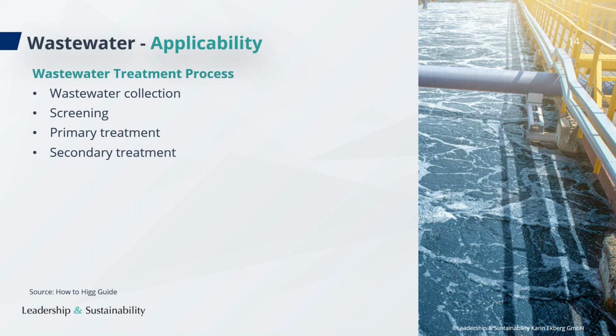bottom of the tank. And in addition to the application of activated sludge, there are also some steps that can be included during this secondary treatment. So there may be aerated lagoons that you can see also on this photo here, biofilm, trickling filtration, oxidation ditches and ponds, etc. So there are many ways technically to solve this or to use this process.